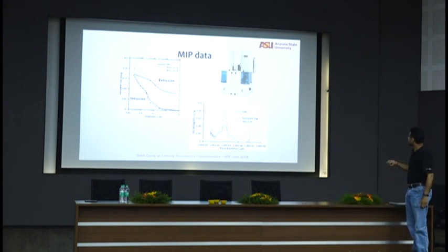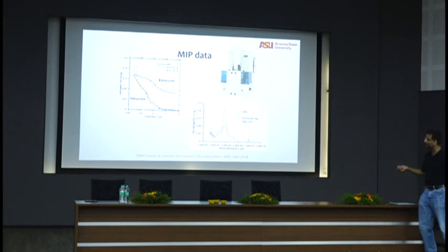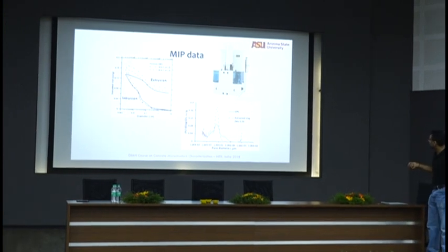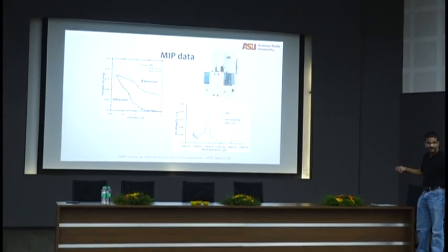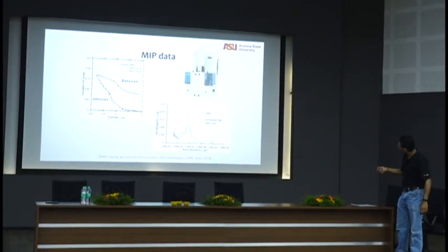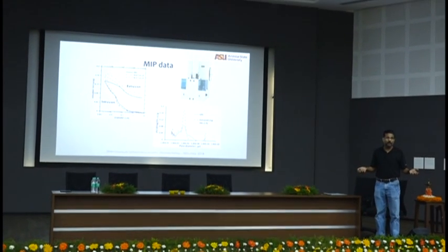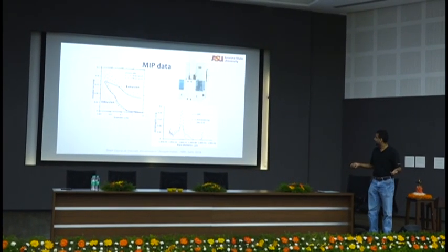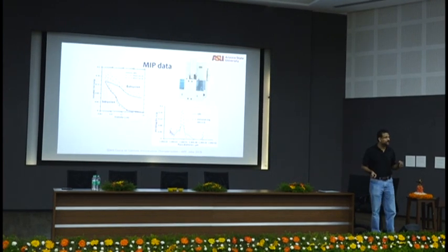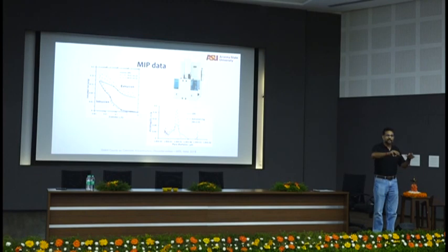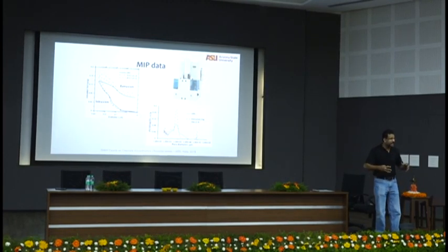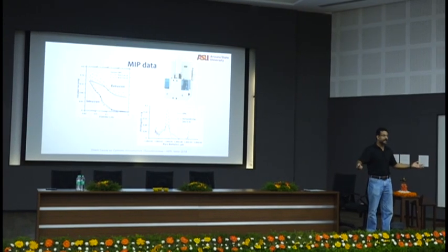Therefore, the more to the left this curve pushes... Now think about it. Now this OPC and alkali activated slag, really no difference in the size, right? But the more to the left this peak pushes, what will you know? The percolating pore size is much smaller, which means even at a smaller size, it's all connected completely. The more it pushes to the right, you say I need a larger size to be connected.